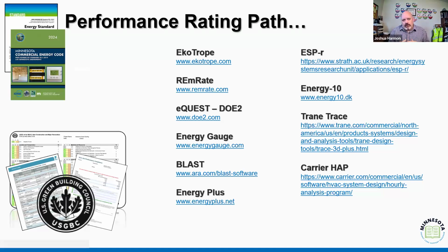So yes, it can be incorporated in a potential design. Let's say you were using a heat lamp in a project, then that would be calculated in some of the Manual J calculations, or some of those mechanical design calculations that get applied to how we redistribute or how we deal with the heat in the heating and air conditioning.